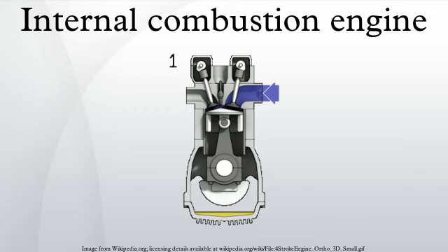Two-stroke configuration. Engines based on the two-stroke cycle use two strokes for every power stroke. Since there are no dedicated intake or exhaust strokes, alternative methods must be used to scavenge the cylinders.